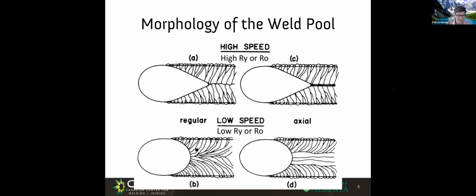And we can tell in the solidification structure whether we were welding fast or welding slow by seeing the structure of the columnar grains from solidification. This is pretty cool. The people who get deep into the issues of metallurgy need to know this fast versus slow business because of this segregation that causes impurities.